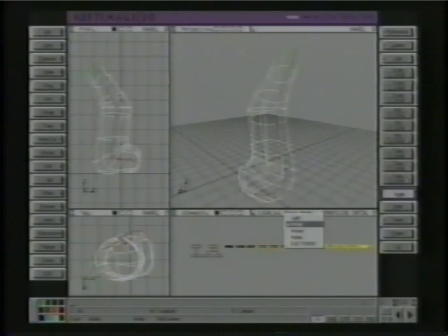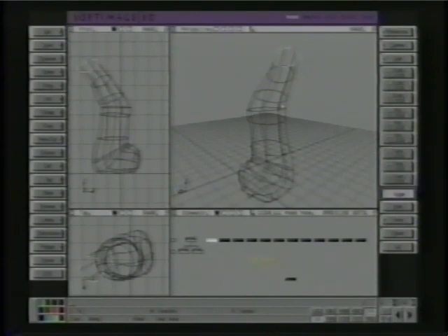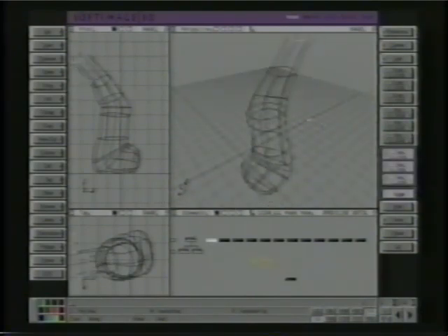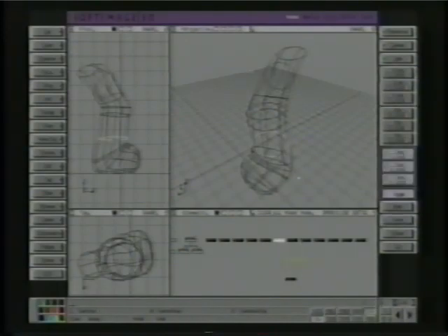And now if I change this to model mode, I'm going to move that icon down, and as I change any of these, the surface of the leg will update. And that same goes if I transform them any way. Notice that the scaling, it's scaling towards its own center. You can go ahead and change that with Edit Center to Vertices, which I talked about earlier. Through scaling and translation, you have a very unique way of editing the surface this way.